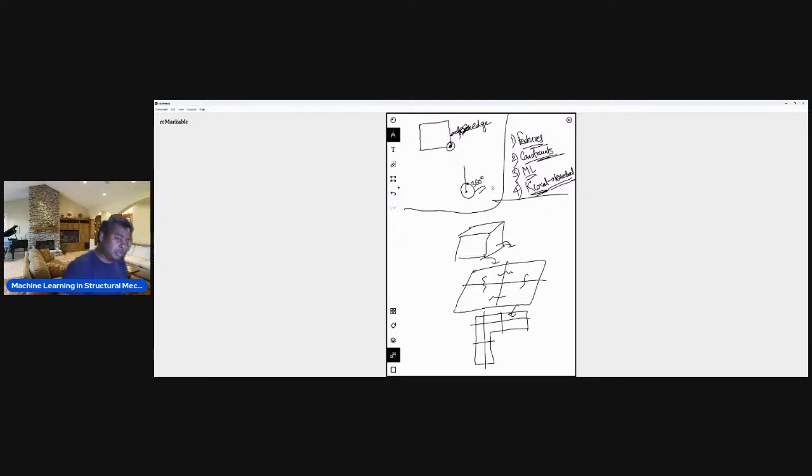And once that geometry is calling different sections of the matrix, based on that we can call whatever is necessary. This is also very useful if you're doing analysis where certain portions of the geometry have a higher amount of nonlinearity, whereas certain portions are still in the elastic regime based on your constitutive law and integration scheme.